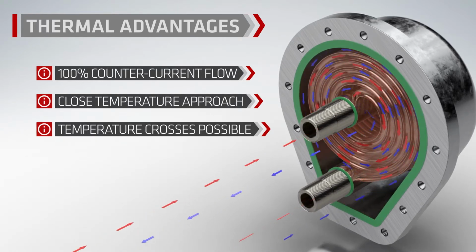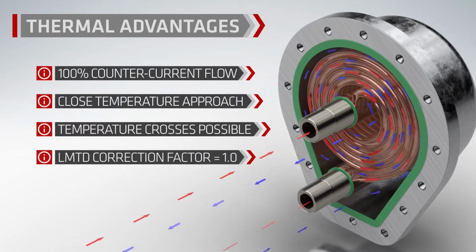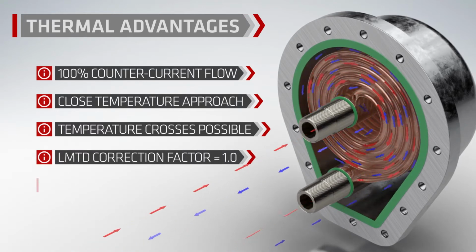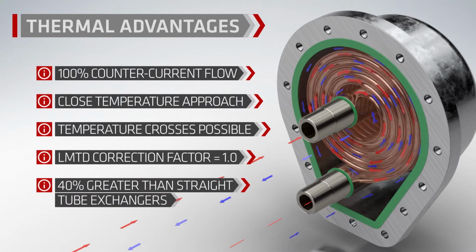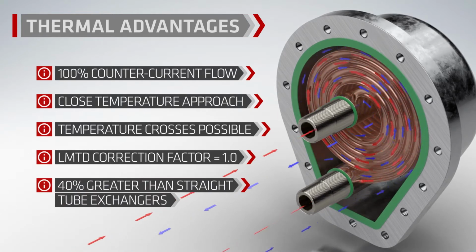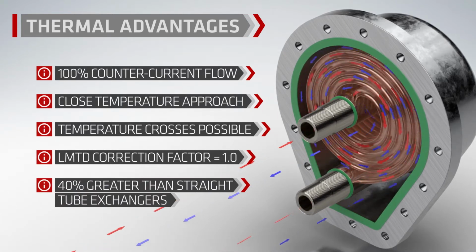Since we have 100% effective surface area, there are no LMTD correction factors. These combined thermal advantages give us a heat transfer rate approximately 40% greater than a traditional straight shell and tube.